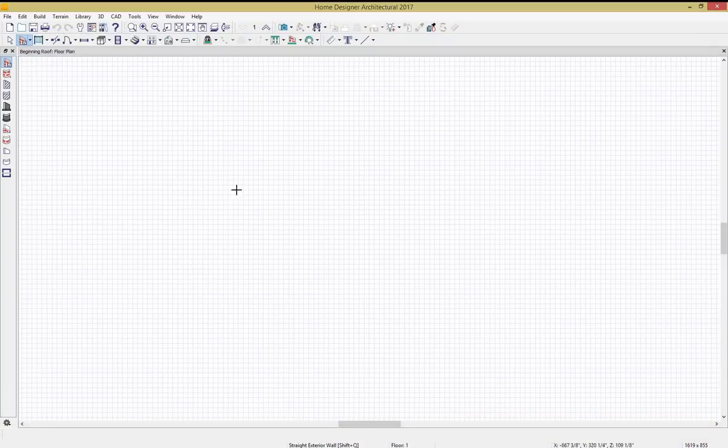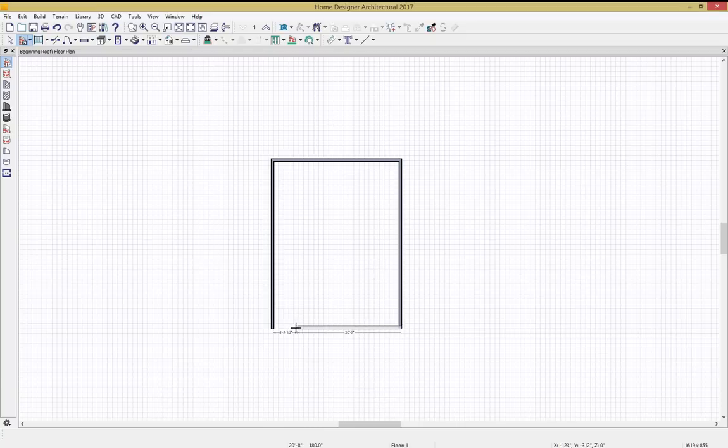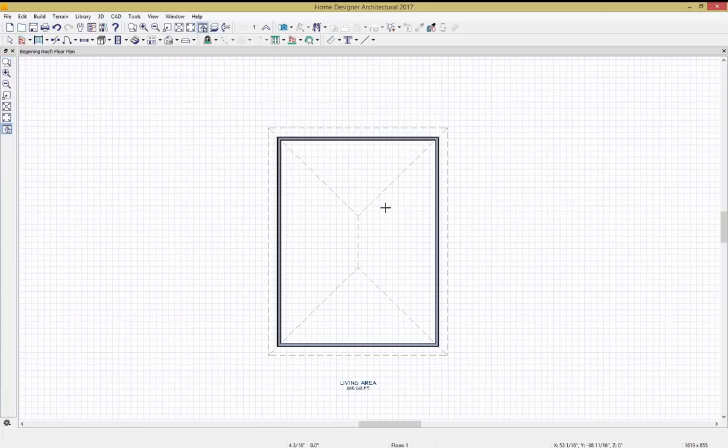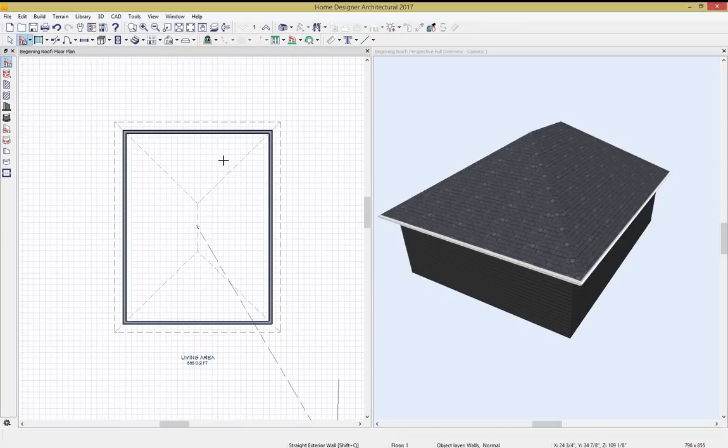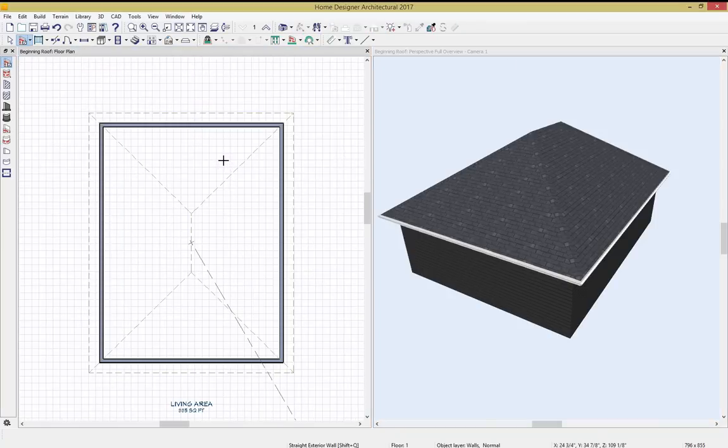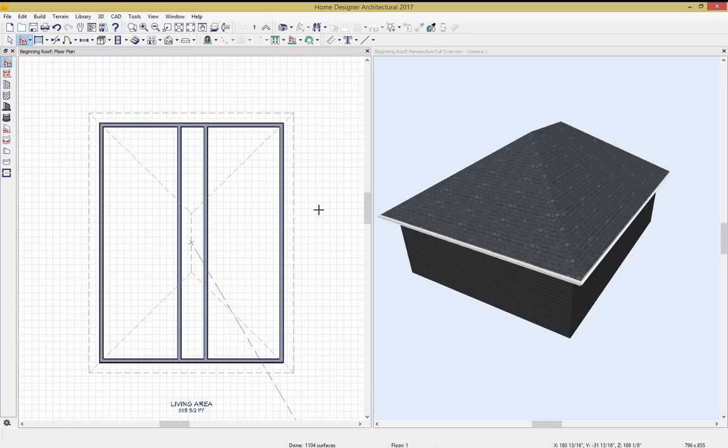So to do this one, we're going to start just by drawing out a rectangle structure again, and as soon as I finish off the room we're going to get our hip structure again. Let's get into our tiled vertical view. So this is where we get a little creative with using our room directives in order to create different roof styles. So I'm going to create essentially three separate rooms. We're going to have a very small room in the center and two larger rooms on either side. Eventually we're going to get rid of the small room, but before we do that,